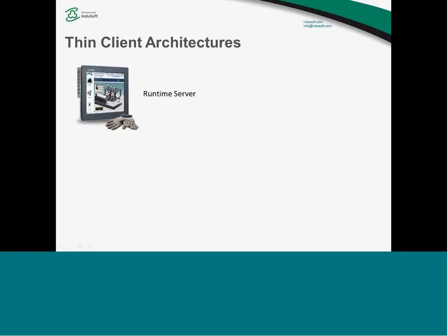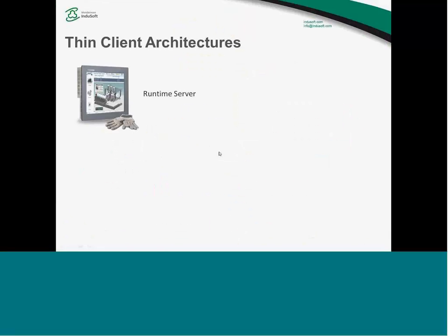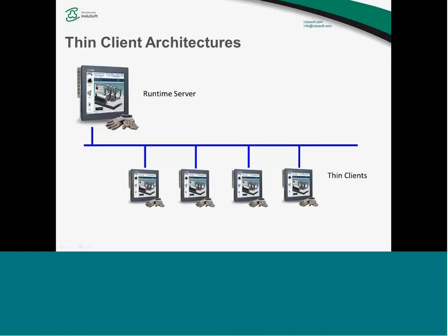If you think of this runtime server as the InduSoft Web Studio runtime, let me go back up a slide. In here, this is the local HMI, although it could really be any of these. What I'm talking about is maybe a local HMI running on a machine. Now I'm going to address these three different thin clients. If we have that runtime server and then a network, you could have multiple thin clients. The first one I talked about, the web thin client, uses Internet Explorer. You can see the screens, the animations and the data, but you see that within the browser window.